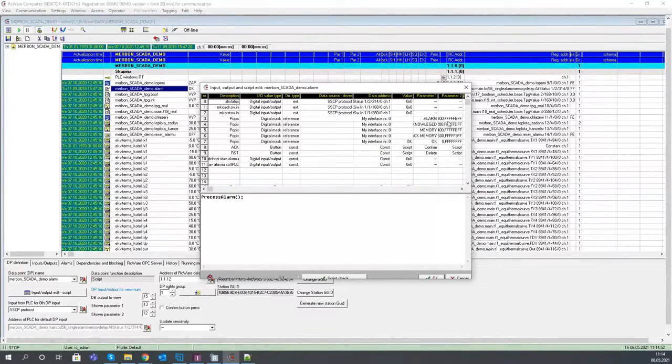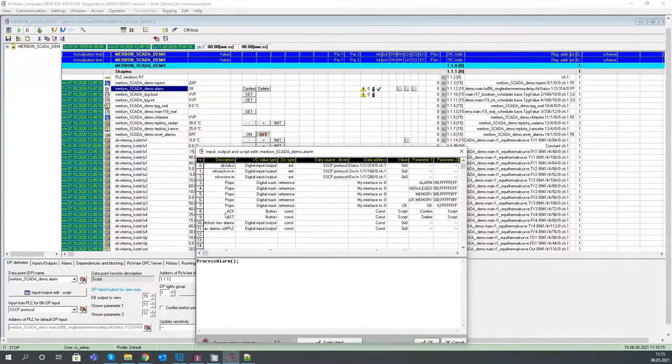It has some multi-state behavior, so it can be in alarm, acknowledged, in memory, acknowledged but still in memory, and normal, like OK. And there is also some activity which is carried out after you click a button, because there are 2 buttons. One of them is called acknowledge and the other reset. You can see that the texts have been changed to confirm and delete. Confirm is for acknowledge and delete is for reset.